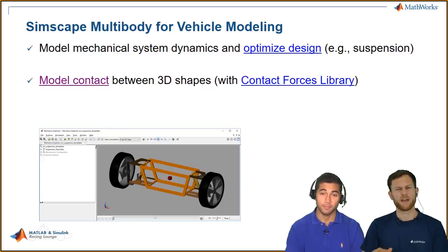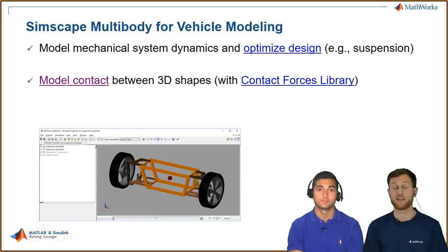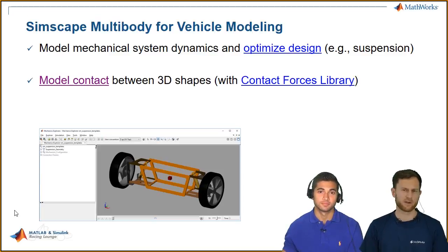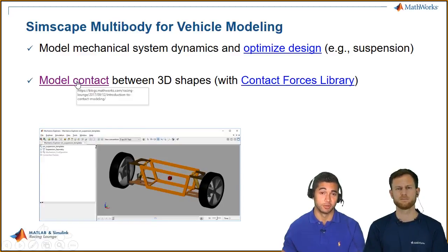Yeah. A comment at that point, so by default, Simscape Multibody does not come with contact, and that's for a reason, because modeling contact takes some CPU resources, and if you don't need to model contact, well, you can save some CPU time by not modeling it. But, well, certainly, we will have a car driving on a track, so contact, friction, tire behavior is important. And the good thing, again here, Sebastian and you have created a nice resource. It's a blog post about contact modeling where we give you the opportunity to explore the details and the theoretical background. Absolutely. Let's take a look at that blog.